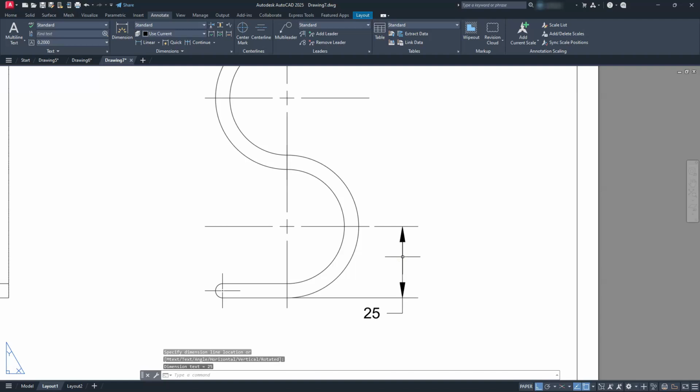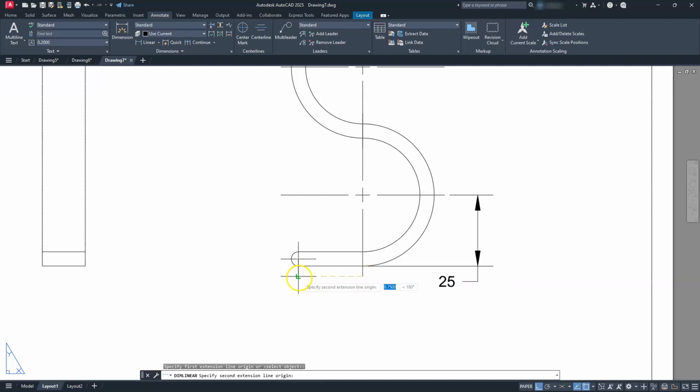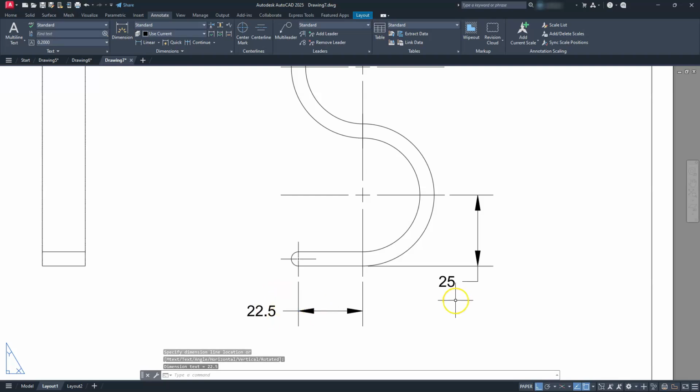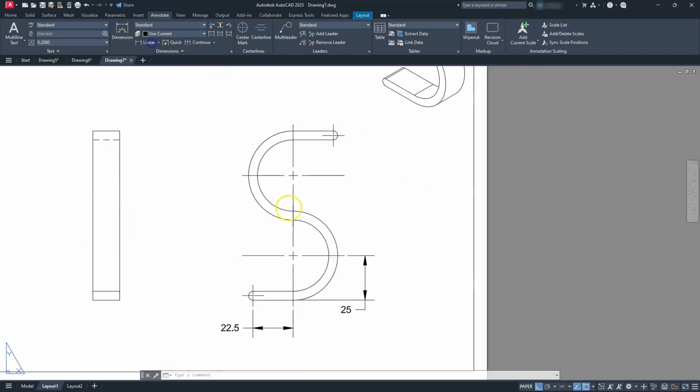So that's kind of one of those sneaky little rules of AutoCAD. If you create your dimensions using that in mind, then it will save you on your keystrokes. So for example, if I know that I want this next dimension here to be going out in this direction, I'll always select this endpoint first, going to this endpoint. And therefore it will kick it out this way. If I select it in the other order, it's going to kick that dimension out here to the right. So that's one of those things you can keep in mind, and it'll help you with your keystrokes, or at least speed up your drawings, and that way you don't have to go ahead and modify those later.